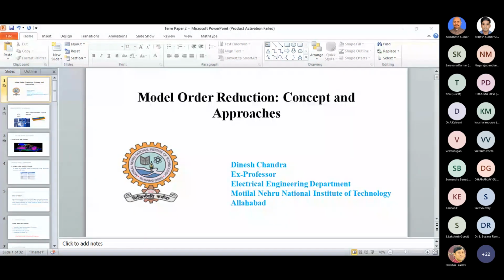Then computation time. The calculation of the control input could take longer than the sampling time allowed. This may lead to reduced control quality and even to instabilities. Then the hardware. The higher the order of the controller, the more powerful hardware is needed.